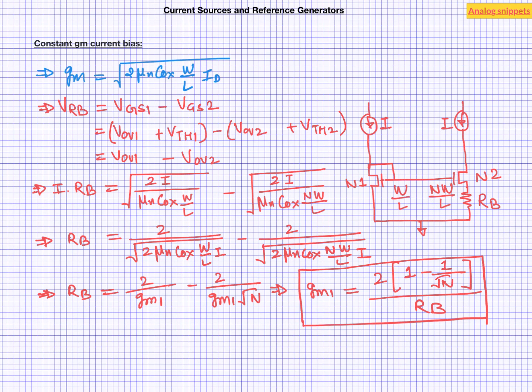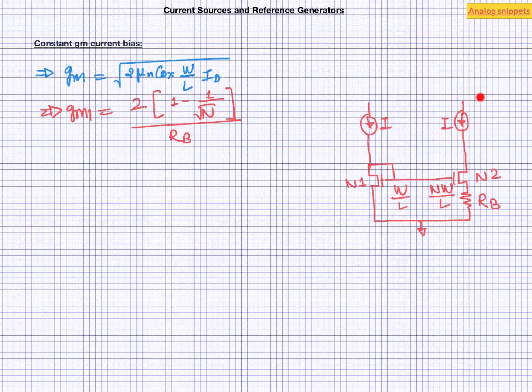So let's look at a couple of schemes to replace these current sources. The simplest way is to replace it with a current mirror, making this whole circuit rather like a current conveyor. In general, this scheme works, but there are some drawbacks. For example, PSR of this circuit is not particularly good. And by the way, just like bandgap, this circuit also requires startup. We can always cascode this pair to improve the performance, but this costs more headroom.